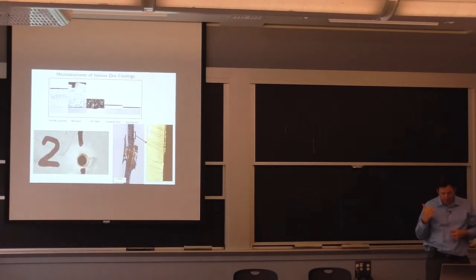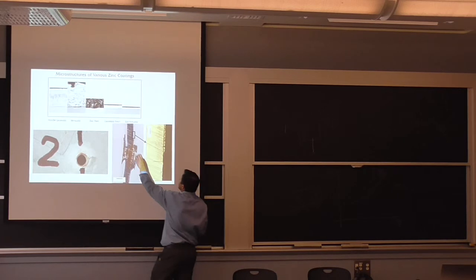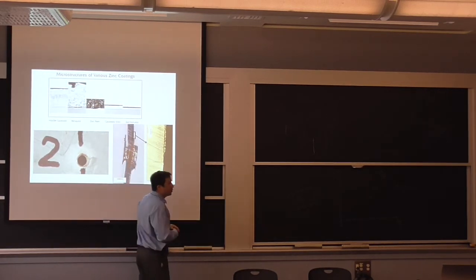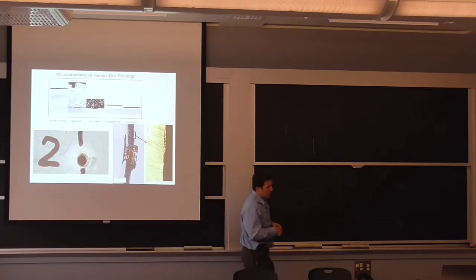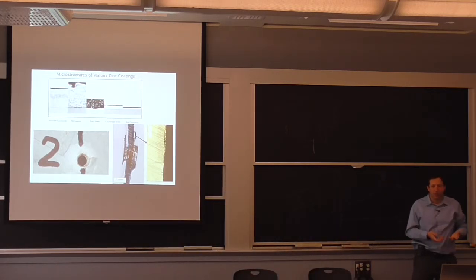In this case, we lost the galvanizing over a distance of about 1/4 inch in only 2 years. So at that point, if we're thinking about a 25 or 50-year life, you could be thinking, well, we may as well just put regular steel if the galvanizing is only going to last for the first few percent of the life.